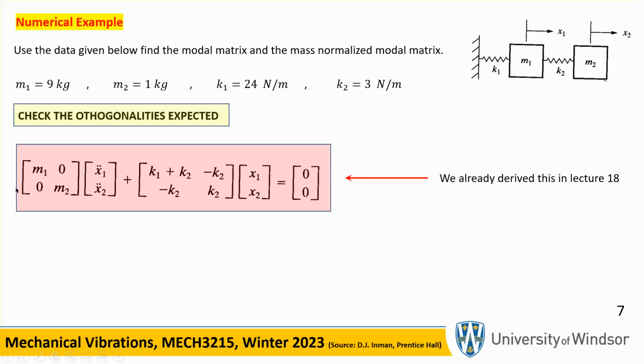So very simple. Just draw the free body diagram, and for each mass, the sum of all the forces is equal to mass times acceleration. You get this. So there is my matrix M, the big matrix M, and there is the big matrix K. This is the mass matrix. This is the stiffness matrix. Notice that the mass matrix, because of the nature of the lumped masses that I'm considering, is diagonal, but the stiffness matrix is not. You can see that.